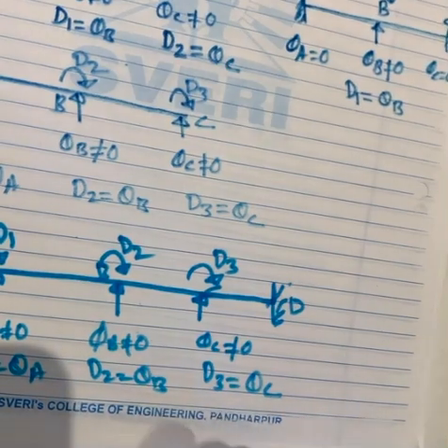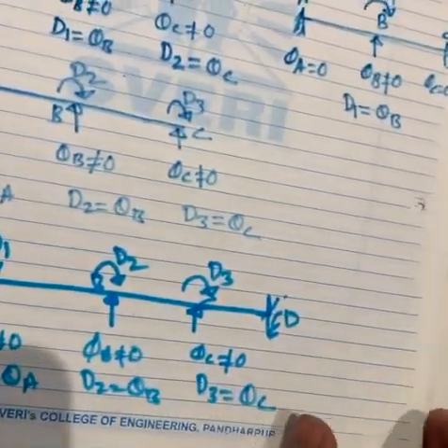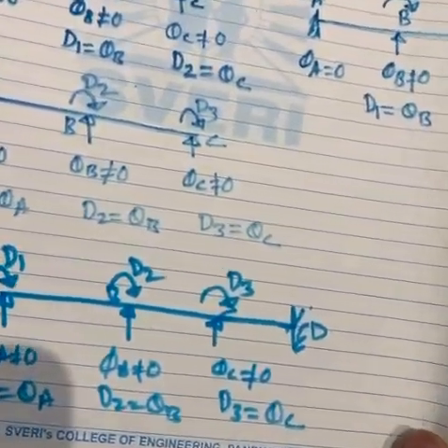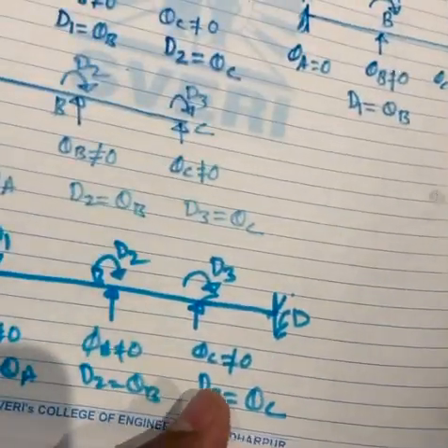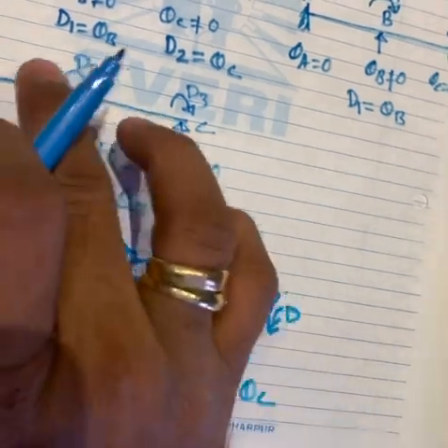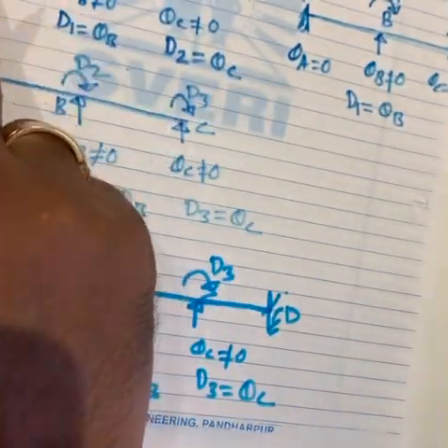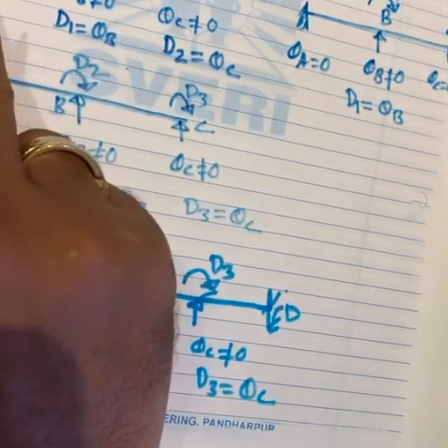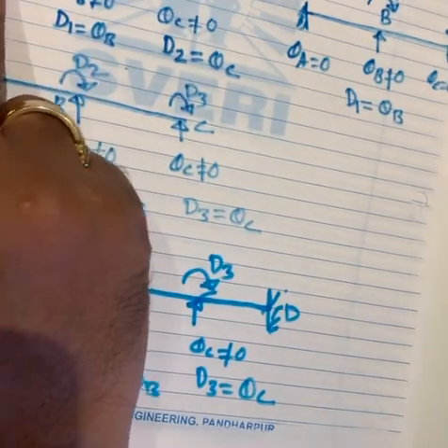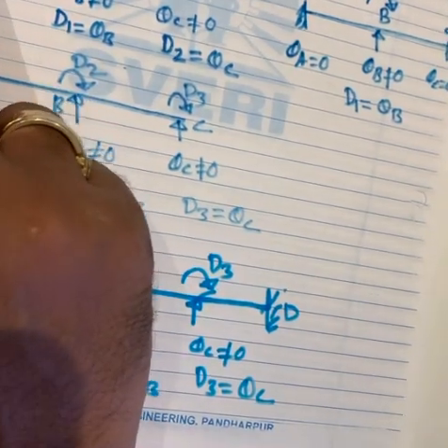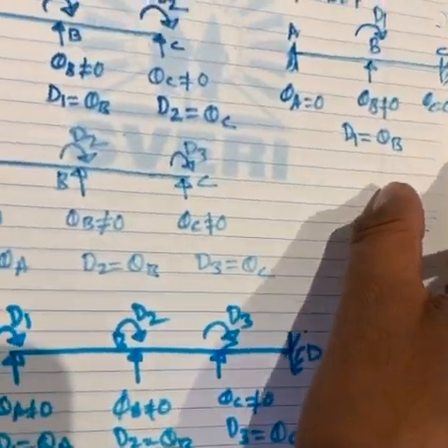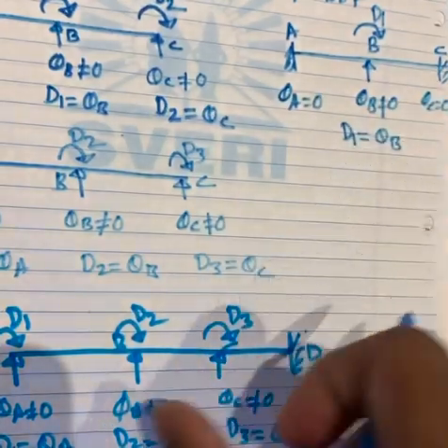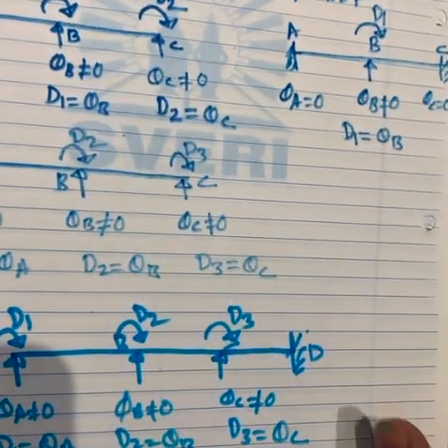So this is how, in step 0, we label the degrees of freedom for each of the nodes. It is very important to understand where there are degrees of freedom and where there are 0 degrees of freedom. Where rotation is not allowed, mainly at a fixed end, there will be 0. As this is a displacement based method, first you will get answers as displacements, that is rotations in this case. So let us go to step 1.